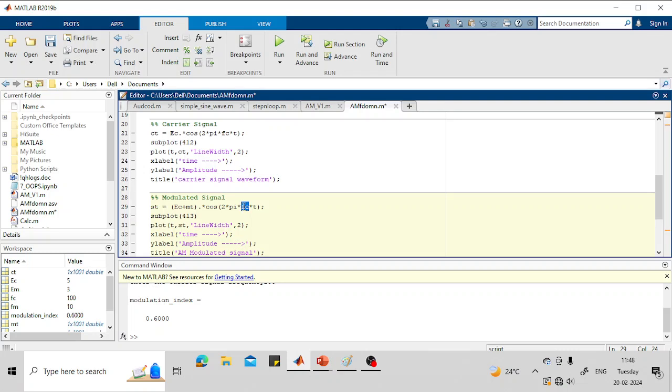Here you can observe that in case of AM modulation, carrier remains constant, and the amplitude is going to change as per the changes in the message signal. That's the definition of AM. So we are fulfilling that AM definition with this formula, and we are storing the variable in S of t or st. The same plot is available in our subplot as the third row plot, fine.